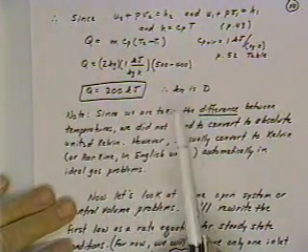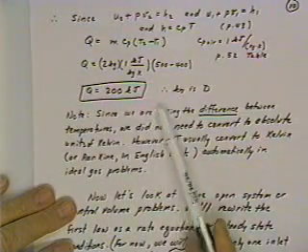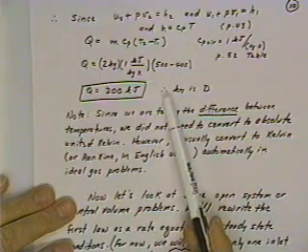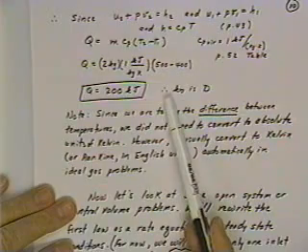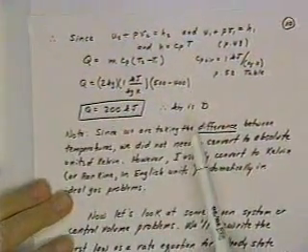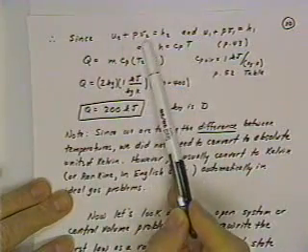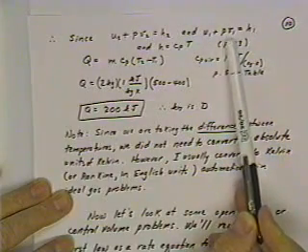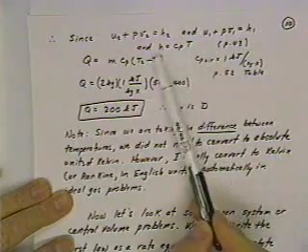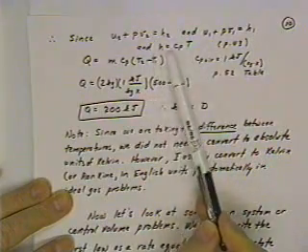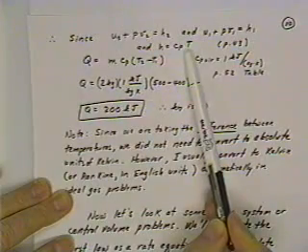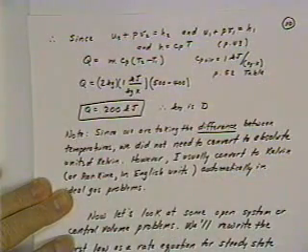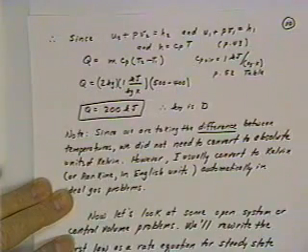And so this problem that started out involving calculations of changes in internal energy and changes in the work term boils down to a much simpler problem. U2 plus PV2 is H2, U1 plus PV1 is equal to H1, and H is equal to C sub P times T. This is on page 43 in your reference manual. So Q then just boils down to the calculation of mass times C sub P times delta T.